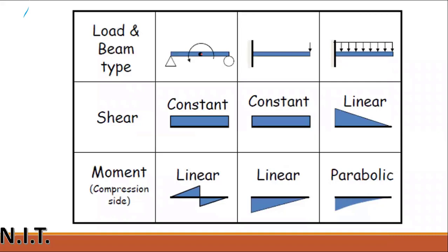Similarly, if a pin or hinge is supported inside the beam, then the shear force will be constant, or rectangular in shape, and its bending moment will be in this way. It will also be linear.